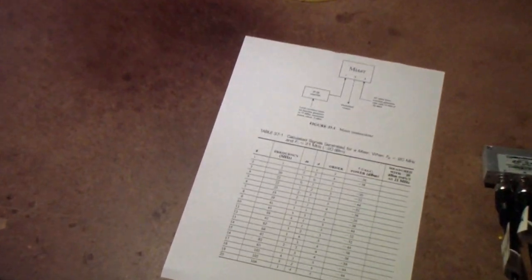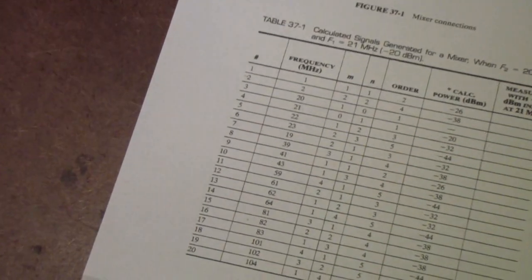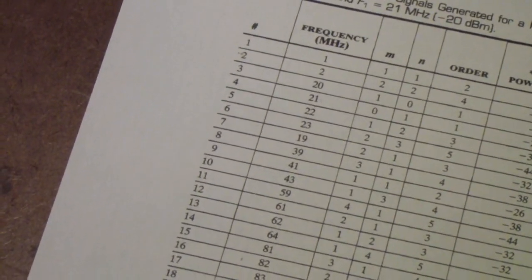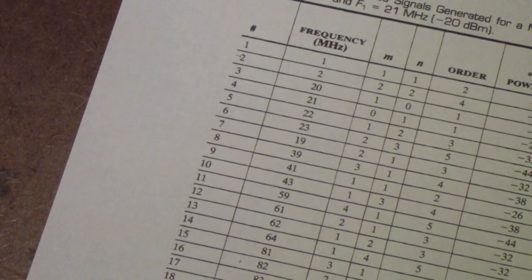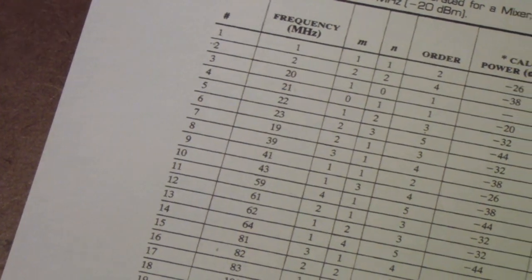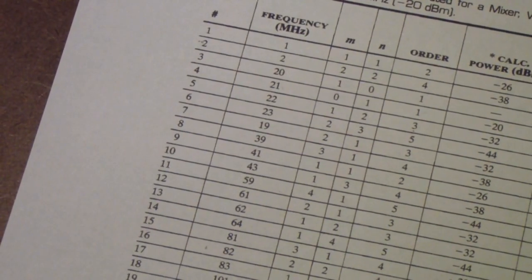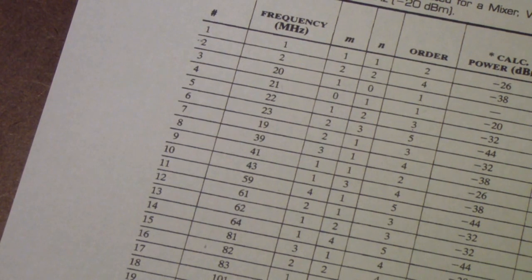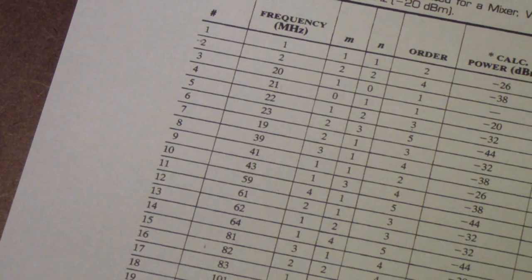Now what we're going to do is move out, and we're going to do measurements of a number of frequencies that are shown there that are above 1 megahertz. We'll look at 2 megahertz, but only cursorily, and then we'll look up at the components at 20, 21, and at higher frequencies. The sum, of course, will be 41 megahertz, so we'll want to go to at least 44 megahertz.